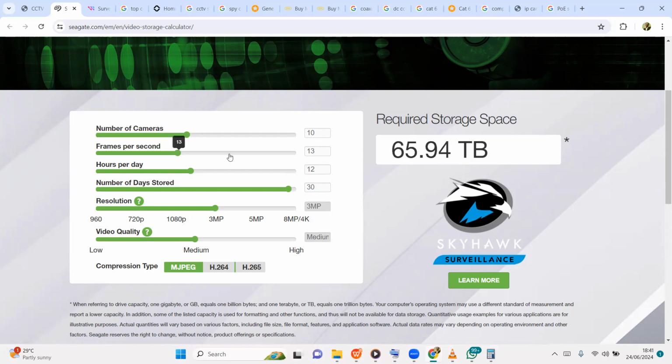That's why it's good at times to set up your cameras to only record when they detect motion, especially if you're using those kinds of cameras. Not all cameras can do that, or not all NVRs can do that, but it takes less space. If you're recording, let's say, an average of 5 hours per day, or 4 hours per day, it only picks up signal when it sees people or a motion. But if it's going to be recording completely, then you're going to need a whole lot of space.